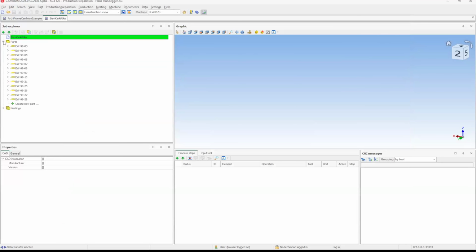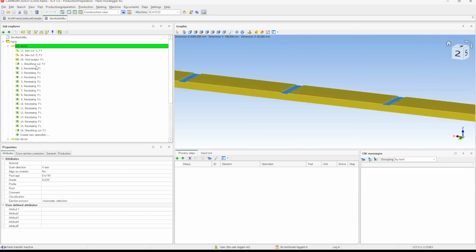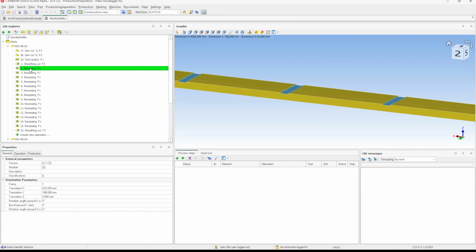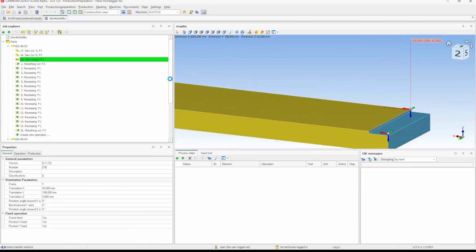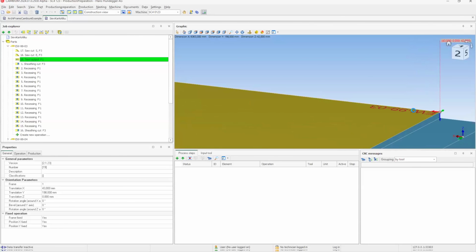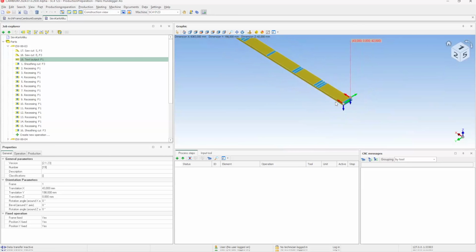So this is how the cut saw sees things. The bottom plate has all these grooves, and we also have the text here showing the blank ID. In a factory, typically everything is printed and labeled. So if there is one blank lying around, you know from this ID, external wall 99, that it belongs to this element, and inside the element it is part number 3. That will be marked directly on the wood when going through the CNC cutter.